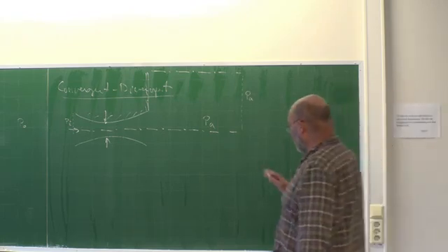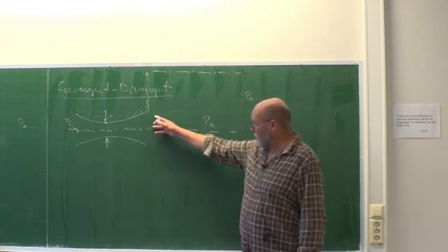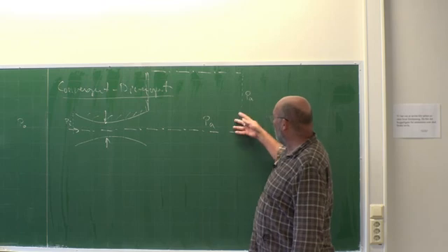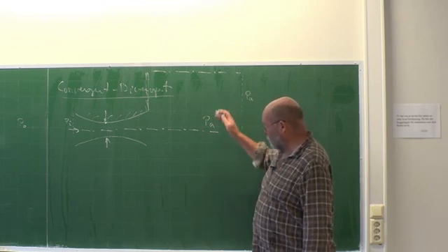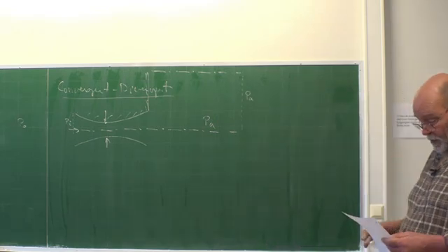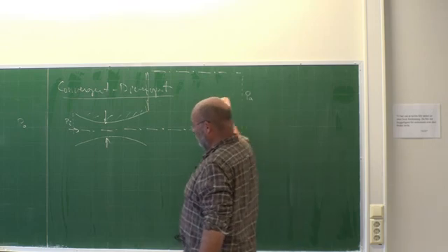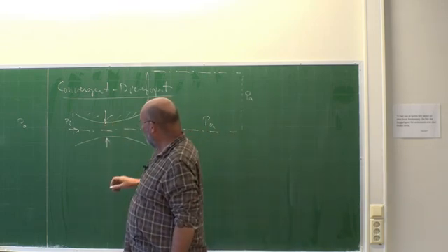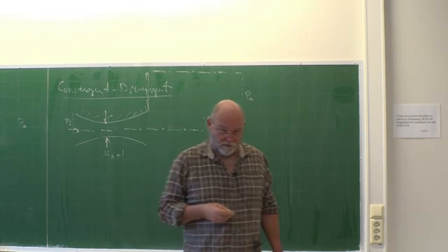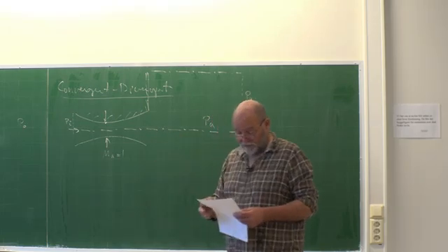And yeah, this area has to be somewhat big because the shock structure is going to expand and develop in this range before it flows out. So this should be your geometry. And well, if it's choked, you have a strong enough driving force, then in this area here you will have a Mach number of 1. The question is what's going to happen afterwards when you are in this region.